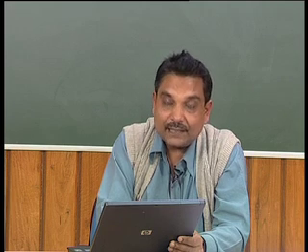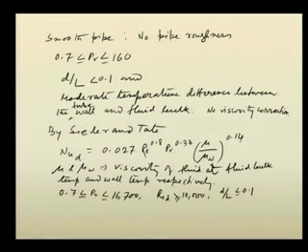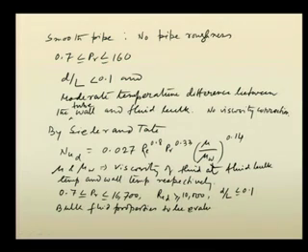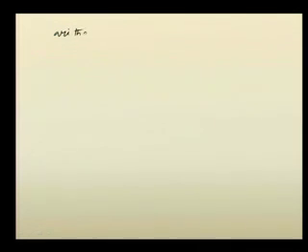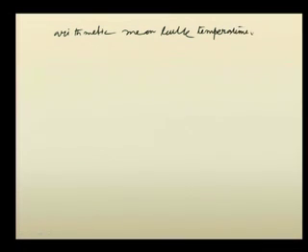These physical properties, or bulk fluid properties, are to be evaluated at the arithmetic mean bulk temperature, that means the average of the inlet and outlet temperature of the fluid.